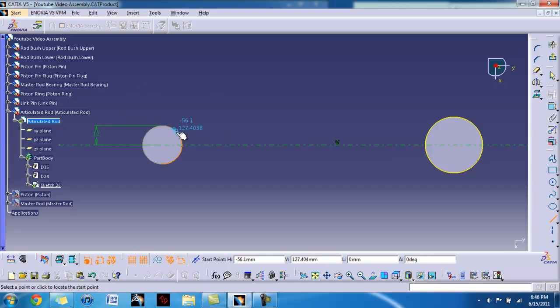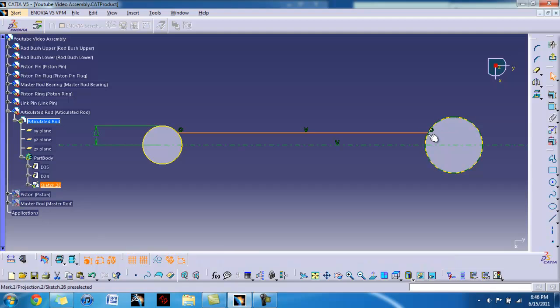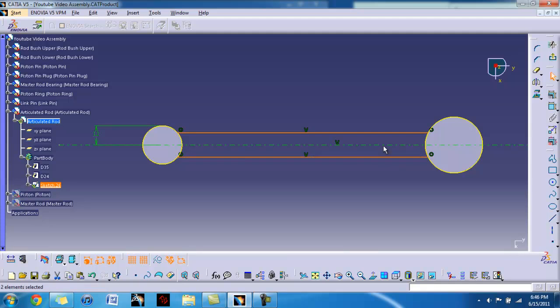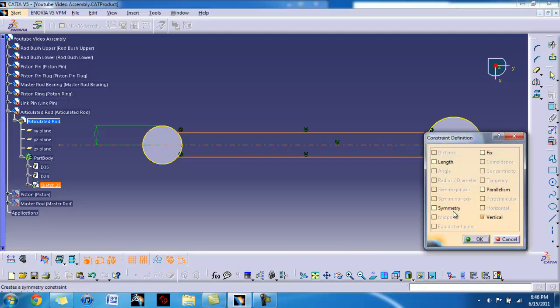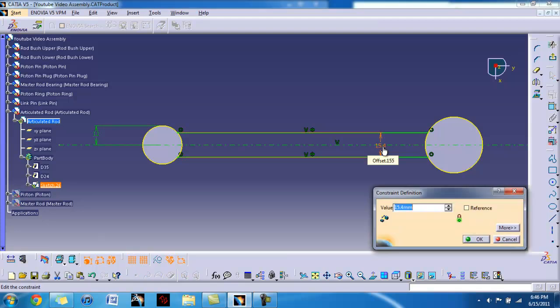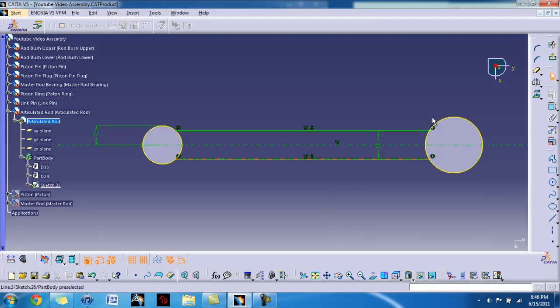And you're going to make 2 straight lines. Make sure they're concentric and they stay blue, meaning that they're vertical or are straight. Alright, using the control key, select the 2 lines in your axis. We're going to make them symmetric about the axis, and then we're going to constrain them. Now we're just going to trim the part of the circles that we projected out that we aren't using. Make sure to keep the ones that are in the sketch.